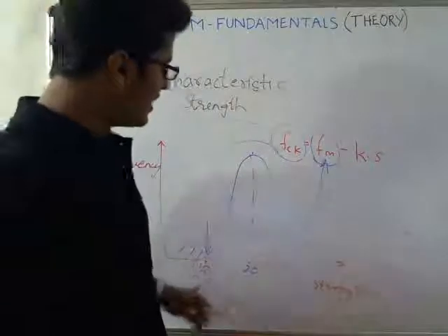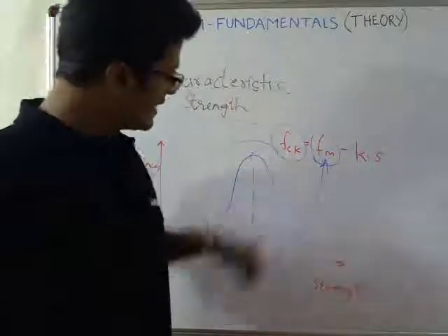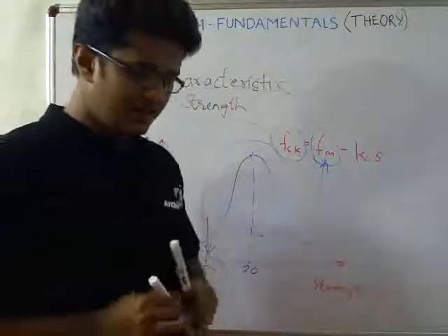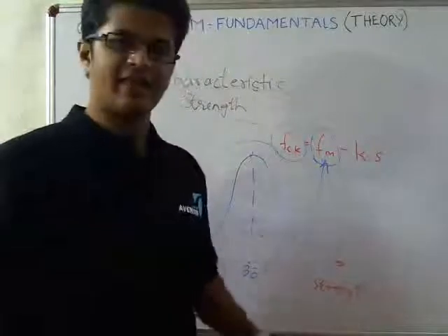That is the reason why the FCK value will be considered as 15 and the grade will be given as M15 grade.